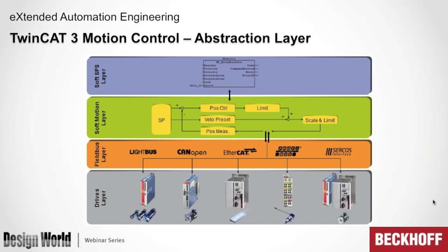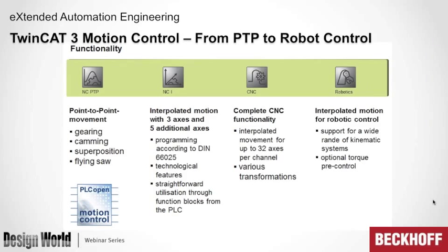And our whole system has always been built on this, but now we're starting to build control systems completely using this, using lots of objects to try to abstract ourselves from the complexity of the system. And for motion, we can do the whole gamut from simple point-to-point to interpreted language where I can give a radius and a point and say move in the circle, and it does all the math for you, to full-blown CNC.